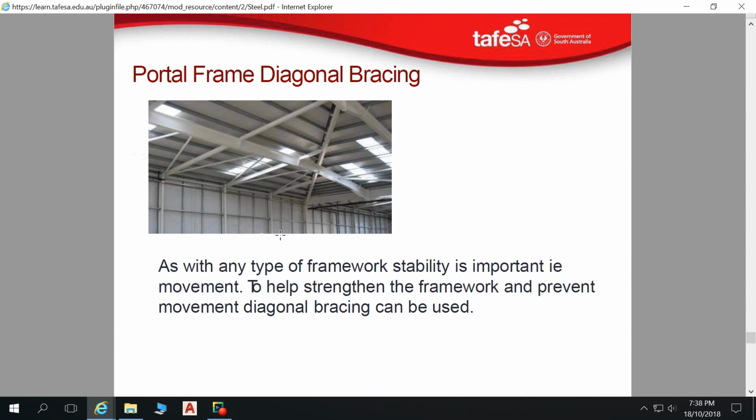Following, and I'll draw it up there. Unfortunately, people at home can't see this, but really it's the only way to show it. We've got some bracing like this. Now we've got wind direction from this way. That bracing is being stretched.